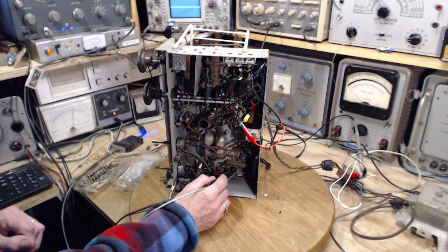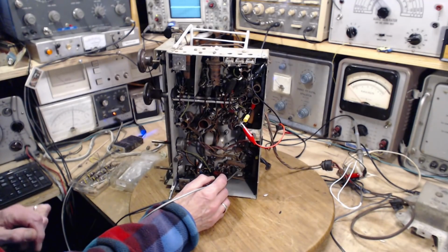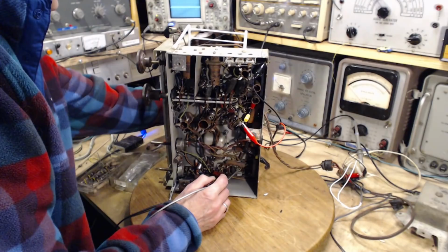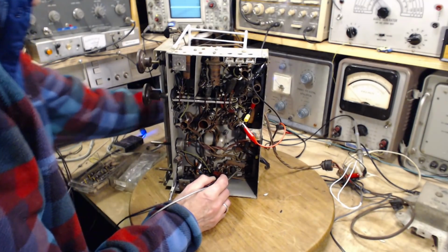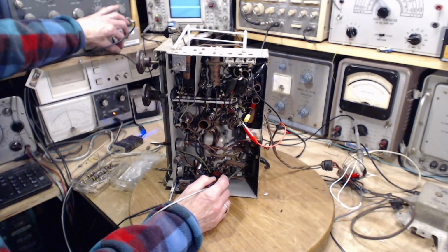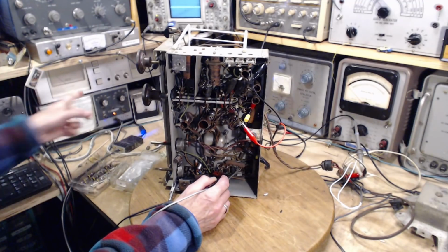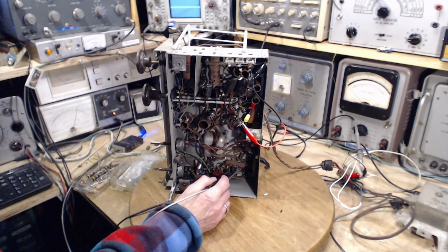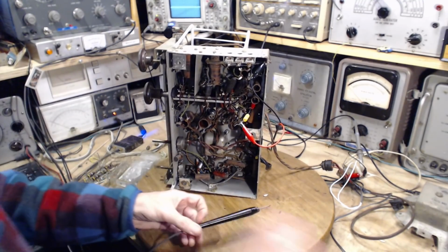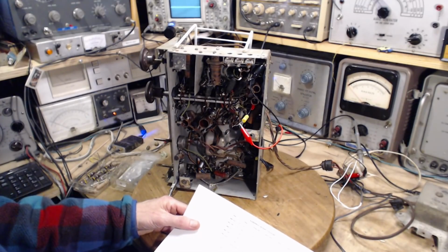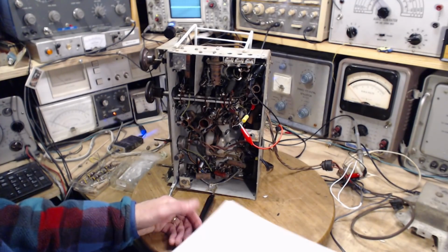Why don't we give it the full Monty here and just see what happens. Okay, full Monty. Okay, so I'm going to stop going through the dim lights. Well, that's quite a difference. Oh, went up, coming back down. So we're still hanging around 100 volts here. Well, they're right around 100, and they really want 195 there. So there's something more going on.